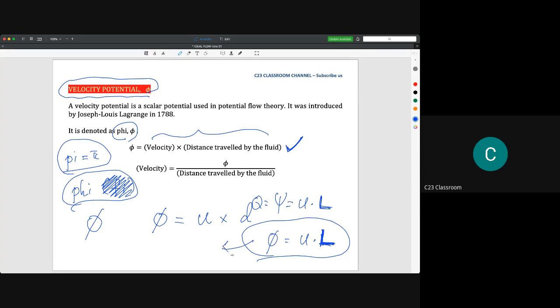As I said, the simple assumption is that they proposed this equation by using similarity. You know the similarity that you learned in fluid mechanics 1, the Buckingham pi theorem and so on. We assume that the velocity parameter here is not easy to change because it represents the way fluid molecules move. The only way to change is to change the geometrical parts.